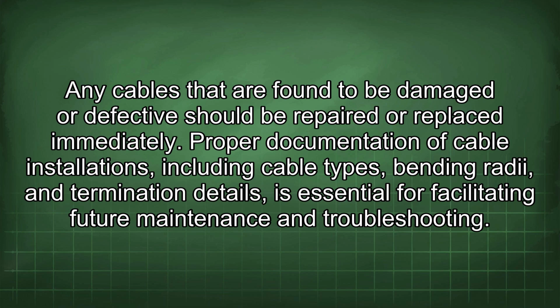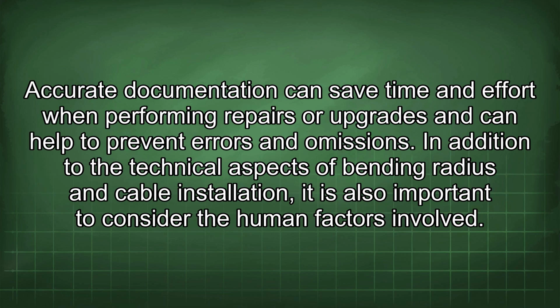Proper documentation of cable installations, including cable types, bending radii, and termination details, is essential for facilitating future maintenance and troubleshooting. Accurate documentation can save time and effort when performing repairs or upgrades and can help to prevent errors and omissions. In addition to the technical aspects of bending radius and cable installation, it is also important to consider the